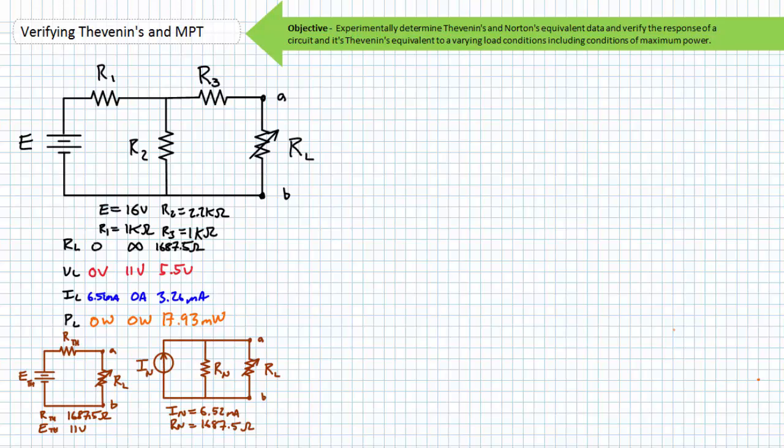Remove the voltage source first. Then connect the 2 terminals it was attached to with a wire. Do not short circuit the voltage source. Doing so would cause your lab instructor to fly into a justifiably homicidal rage. Power off the voltage source and remove the voltage source. Then short circuit the original circuit.